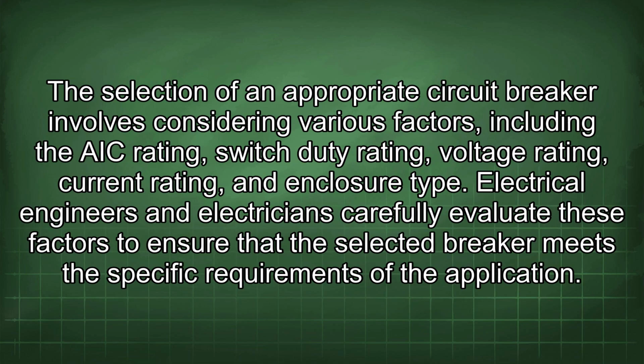The selection of an appropriate circuit breaker involves considering various factors, including the AIC rating, switch-duty rating, voltage rating, current rating, and enclosure type. Electrical engineers and electricians carefully evaluate these factors to ensure that the selected breaker meets the specific requirements of the application.